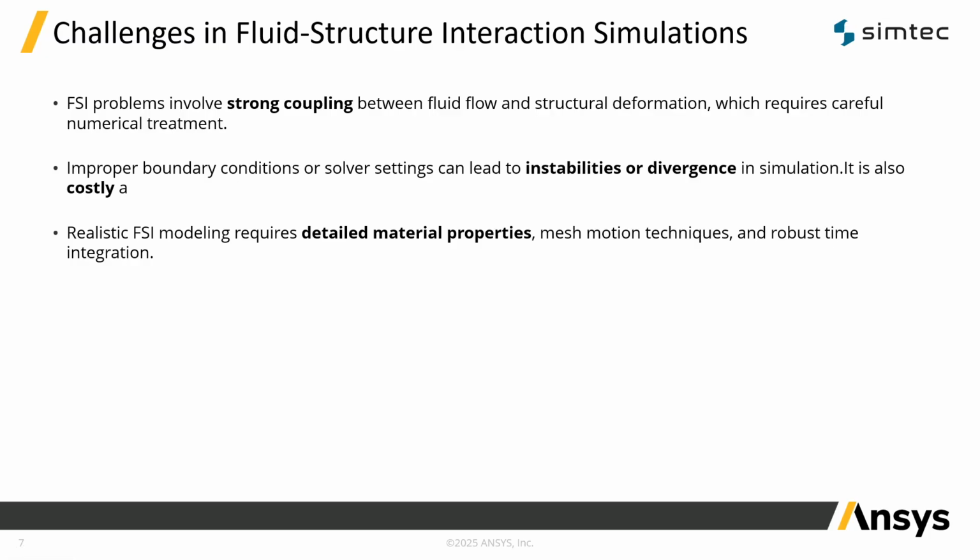Despite its value, FSI simulations are numerically challenging. Strong coupling can lead to solver instability. Poor boundary setup may result in divergence. Mesh motion or distortion must be carefully managed. So, you will need robust solvers, smart meshing strategies, and powerful processing capabilities. That's where LS-Dyna stands out.